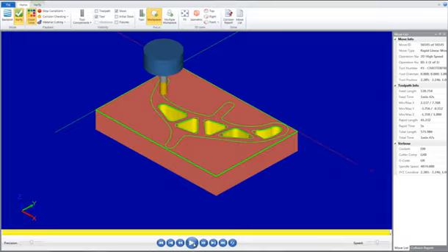Your part will appear as shown up to this point. Verify mode shows the path the tools take to cut the part with material removal. This display lets you spot errors in the program before you machine the part. As you verify toolpaths, Mastercam displays additional information such as the X, Y, and Z coordinates, the path length, the minimum and maximum coordinates, and the cycle time. It also shows any collisions between the workpiece and the tool. You can now exit Verify.